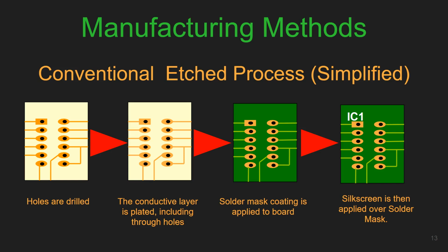And then place the PCB into the etching solution and agitate for 25 to 30 minutes or until all the copper has dissolved around the design. And once all the copper is gone, rinse it in the water bath and let it dry, and use rubbing alcohol to wipe off any ink transferred onto the PCB. Now you have an etched PCB, but you still need to drill the holes.